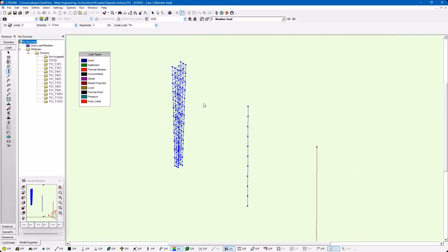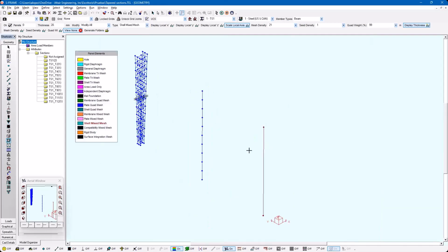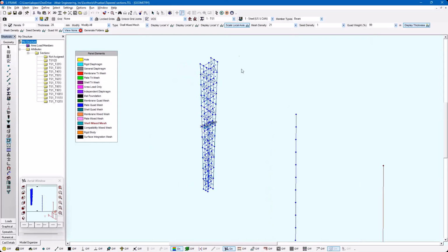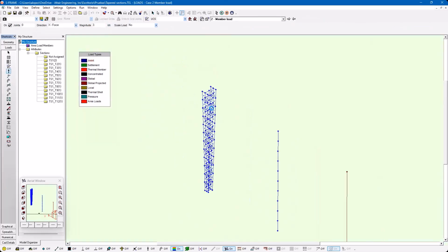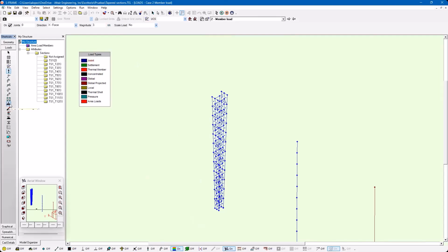So to avoid adding the loads one by one for the panels, I can go again to the geometry window and let loads. And what I'm going to do is go for this part, it says the uniform pressure tool. This uniform pressure tool will help us to define that load for the shell elements that we have right here.